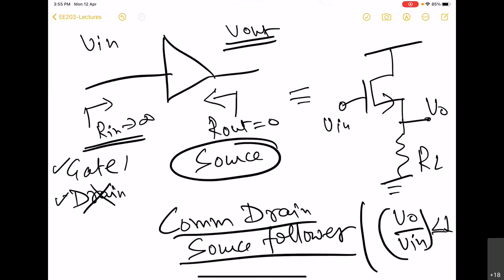So if you want some finite voltage gain as well, because here you can see that we are giving voltage and we are interested in voltage on the output side, then a single MOS cannot fulfill that requirement. It will definitely fulfill this impedance requirement. So we now need to modify this circuit so that we are able to have some finite voltage gain as well.